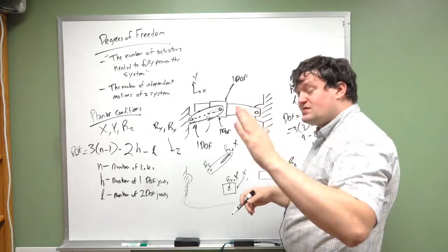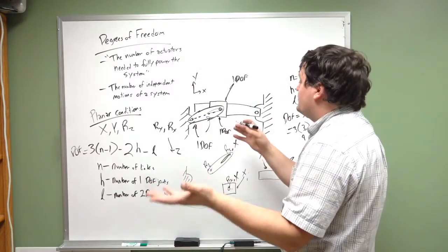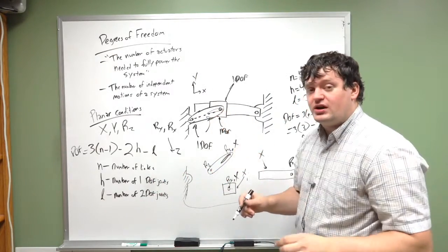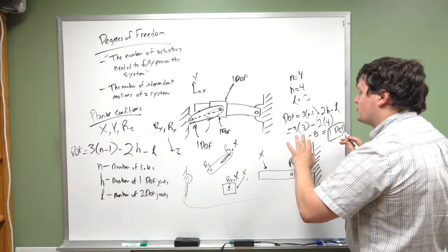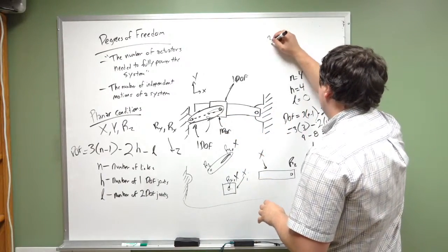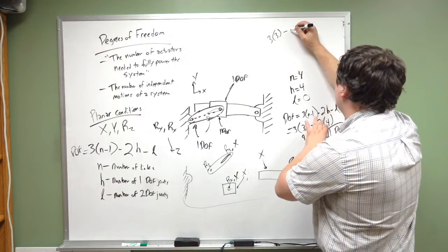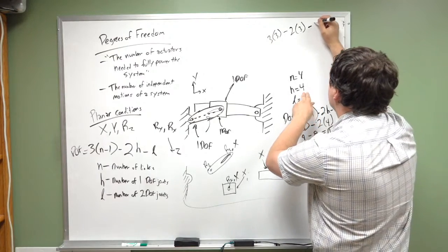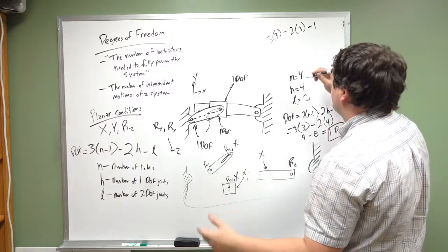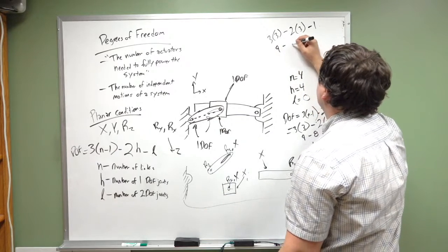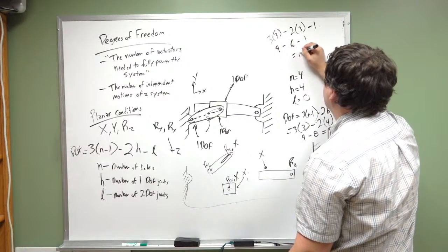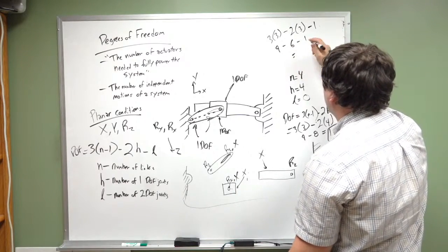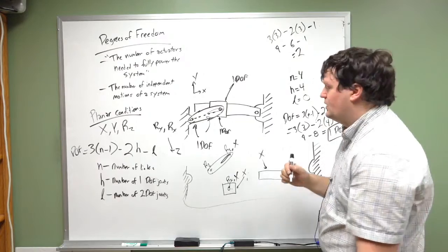And it could slide on the member if you wanted it to, but it wouldn't define anything. So changing this system by adding another degree of freedom in the joint, now if you go back through the math with this now being a slot joint, it becomes 3 times 3 minus 2 times 3, because now there's 3 1 degree of freedom joints, and then 2 degree of freedom joint becomes 9 minus 6 minus 1 equals 7, which means you have, equals 2, because I can do math.